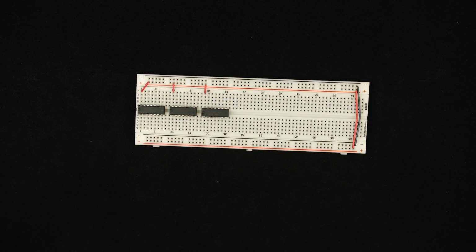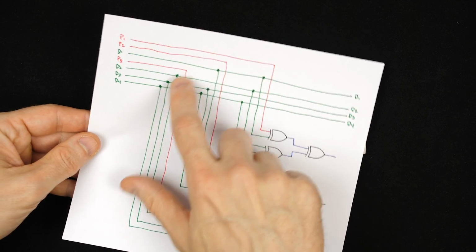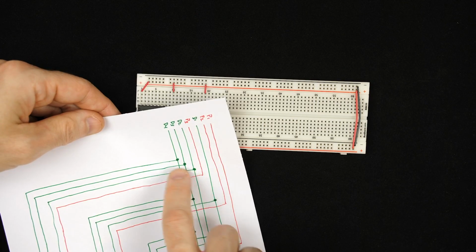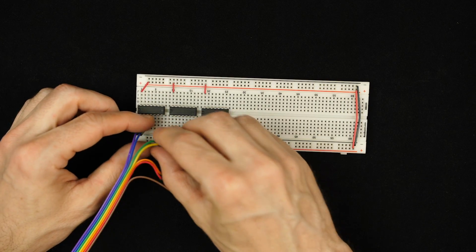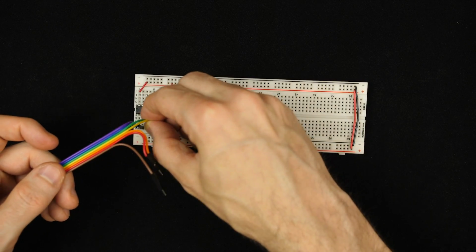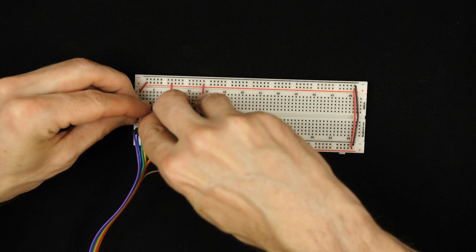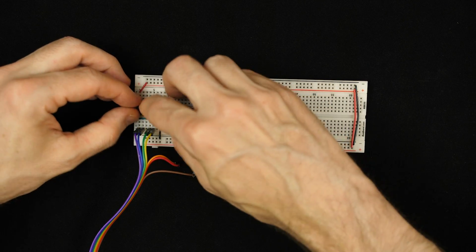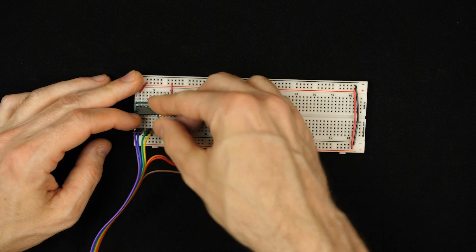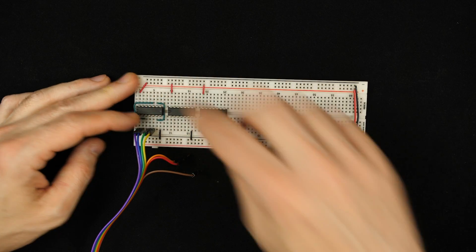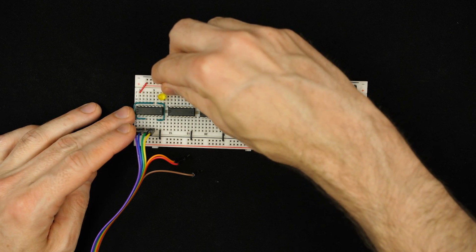And I'll get the power and ground pins hooked up on each of these chips. And I'll start by hooking up this last group here, because that'll be the last 4 bits, which have been on the left, the way we've been laying things out. So I'll put that on the left here. Two of those bits will come into the input of one XOR gate, and then the next 2 will come into the input of another. And then the output of the first XOR gate will come around to one of the inputs of another XOR gate up here on the top. And then the output of the other XOR gate down at the bottom will go around to the second input of the XOR gate at the top. And then the output of that XOR gate we can just hook up to an LED, and that'll let us see what's going on there.